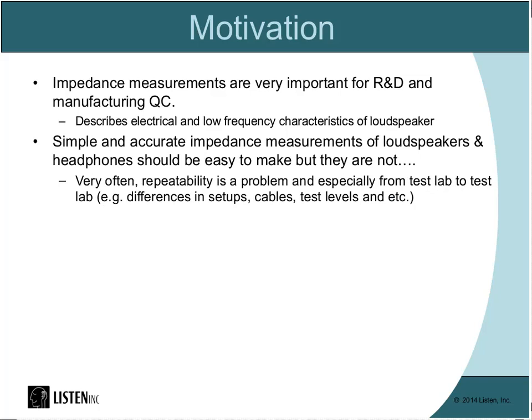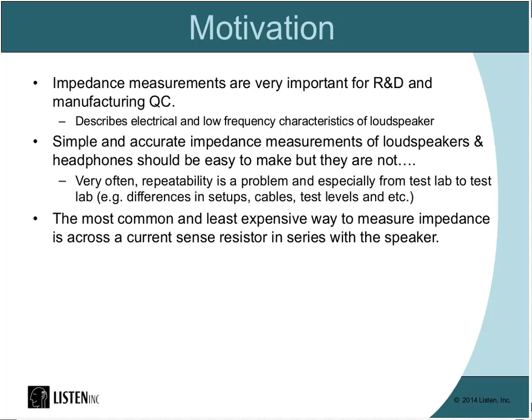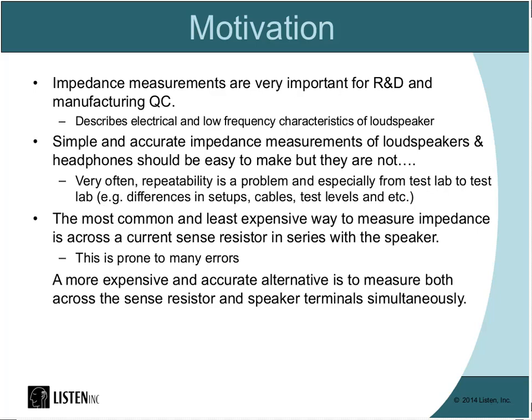I cannot tell you how many times I've visited customers who are having problems with their impedance measurements, and we'll get into why those problems pop up. The most common and least expensive way to measure impedance is across a current sense resistor in series with the speaker. But this is prone to many errors. We'll get into discussing why some of those errors occur.